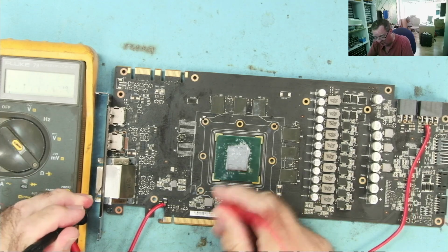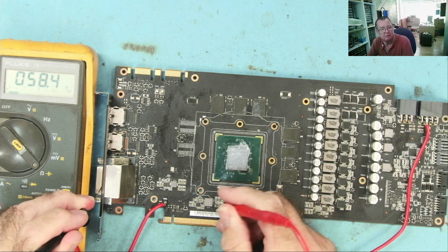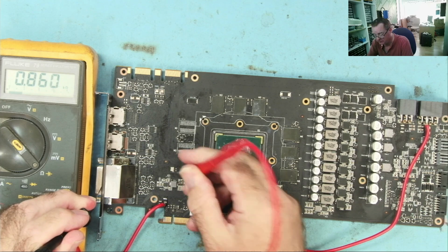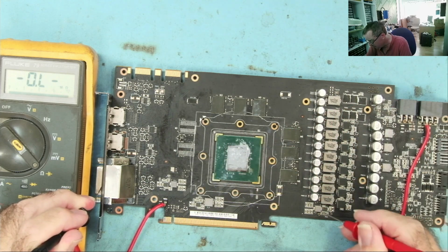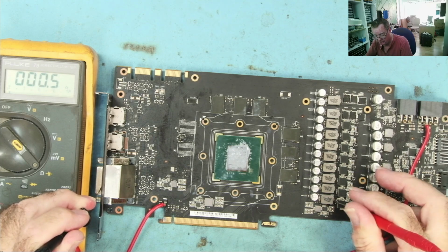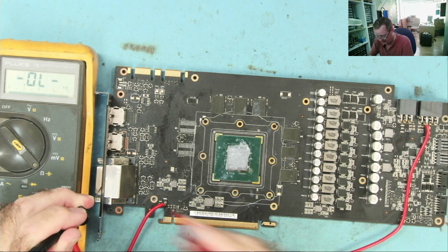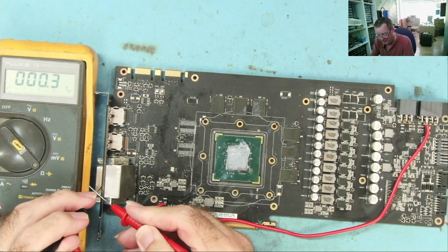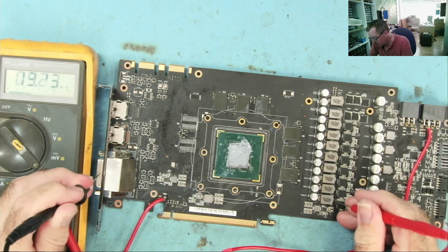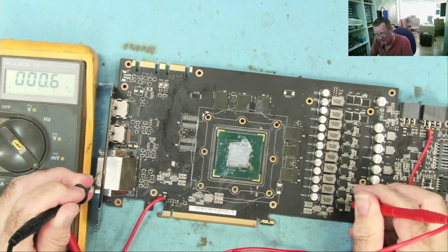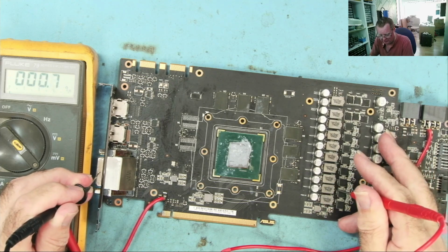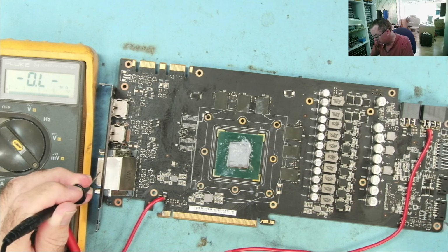So this read very low. No, it's 58 ohms. It's fine, yeah. That's high. Little one here, we didn't measure this one. These are the ones that look like a short. Well, actually it's half an ohm. Now for a GPU like this, it's actually reading 0.3 shorted. For a GPU like this, 0.6, so it's about 0.2 the load. That is not a short when you're talking about high-end GPUs like this one.